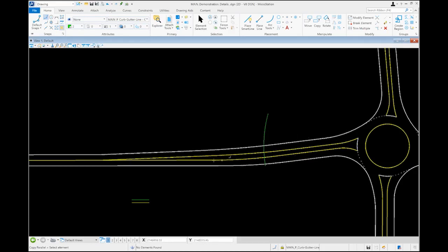Note that for this overall longer splitter island envelope, about half of that envelope would be a raised island and the rest on the approach would be striped out. In this particular case, it may be beneficial to actually extend this island a little bit further away, make it a little bit longer than 200 feet in order to get that curb line along the splitter island through this initial curve, so that we're able to support a little better channelization and speed control coming into the approach.